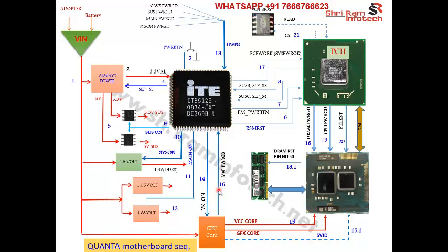Suppose I tell this guy to do this work, so I give him enable. So now he does his job. He finishes that job, and after completing his job, he tells me that yes, I have done my job. That is the confirmation he is done. That is called power good. Similarly, each pulse width modulator has two signals. One is called the enable, another is called the power good.